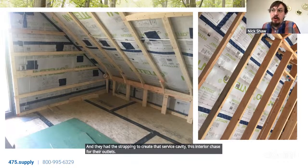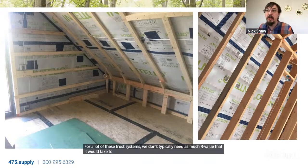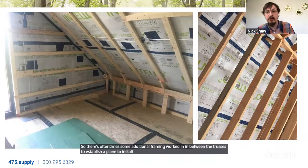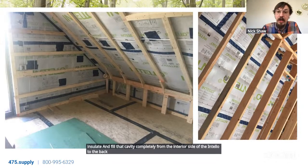For a lot of these truss systems, we don't typically need as much R value that it would take to completely fill the truss. So there's oftentimes some additional framing worked in between the trusses to establish a plane to install the Intello Plus against, so then we can still insulate and fill that cavity completely from the interior side of the Intello to the back side of the sheathing.